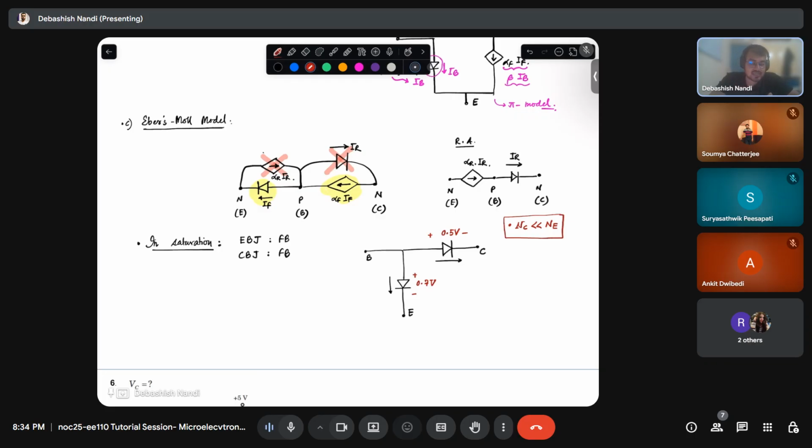That diode check example we have used, right? We were seeing that the base collector junction was having a lower built-in voltage. That's why the cut-in voltage is also somewhat lower than that. So this is ideally how your PN junctions will behave in case of silicon. Fine. Now what I do generally,